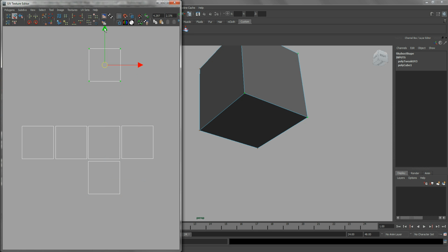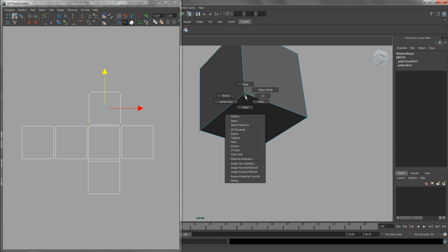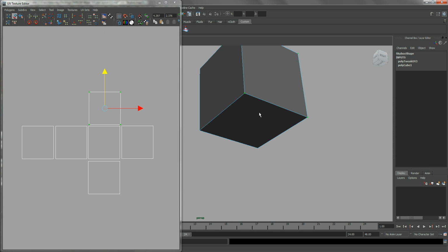So this is telling me that I need to move my UVs, switch it around. Alright, so let me double check again. Bottom right, okay, they are facing the right way, and let me check bottom left. Okay, bottom left, this is not facing the right way, and I will need to rotate it to fit it accordingly. So select the UV shell and rotate twice and rotate twice again. So double check my edge here, so it's facing the right way. Great.